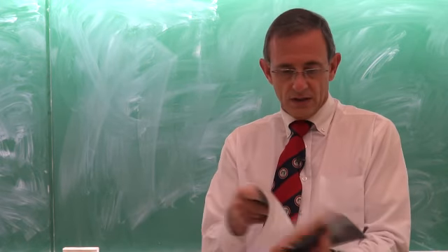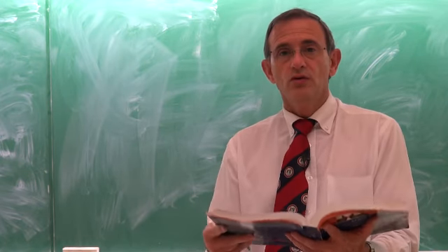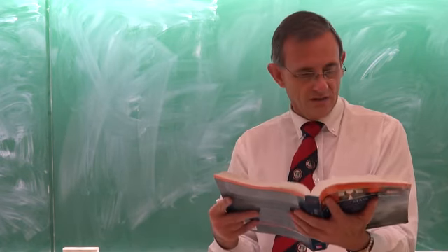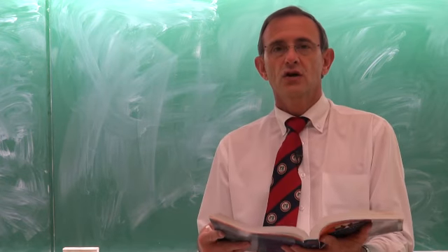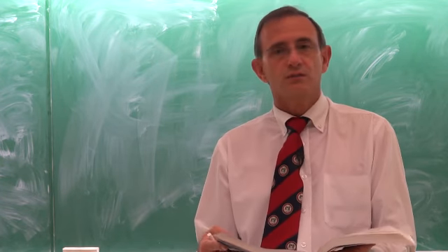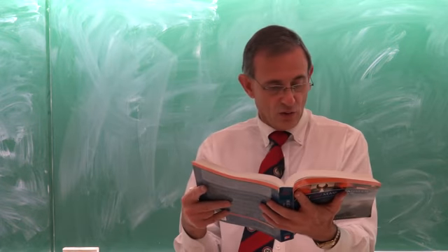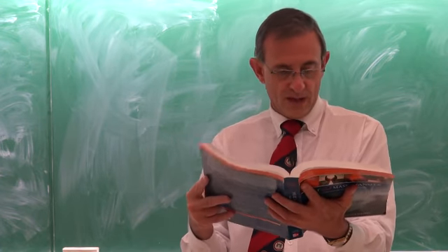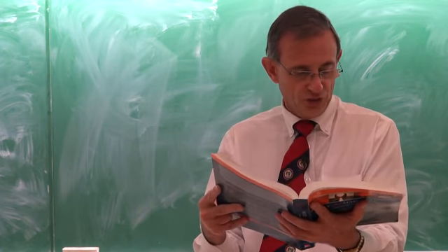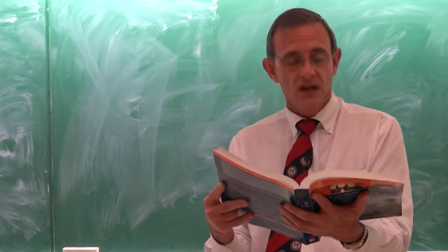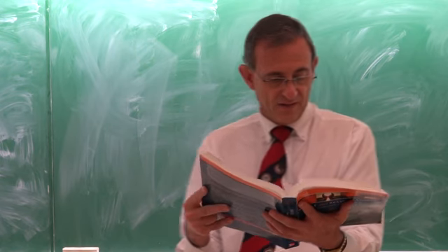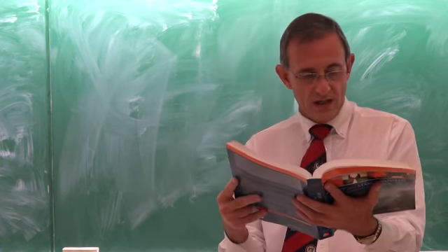Okay, ladies and gentlemen, I would like to do a problem on internal forced convection, and it's from the textbook of Cengel and Ghajar, the 4th edition, and it is problem 8.39. The problem is an 8 meter long and uninsulated square duct of a cross-sectional area of 0.2 meters by 0.2 meters, and it has a relative surface roughness of 10 to the minus 3.